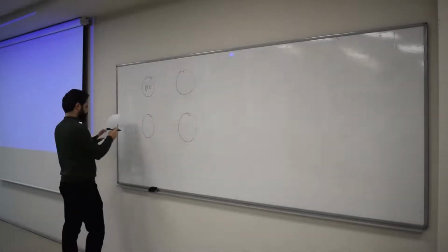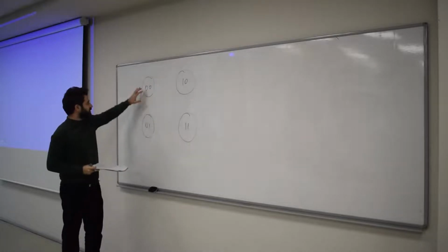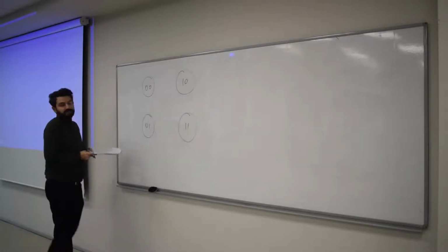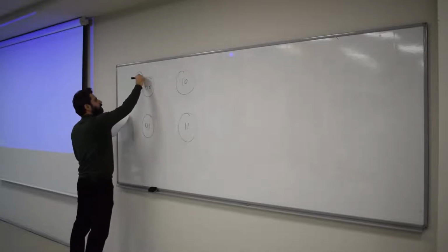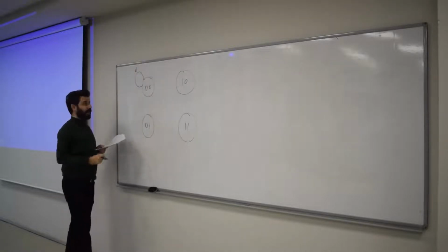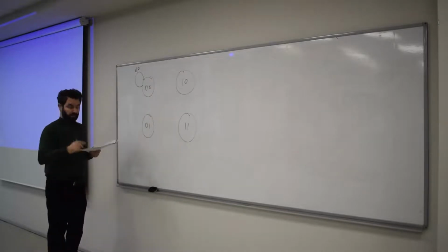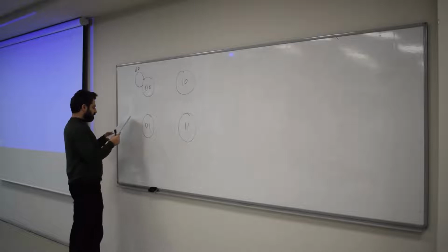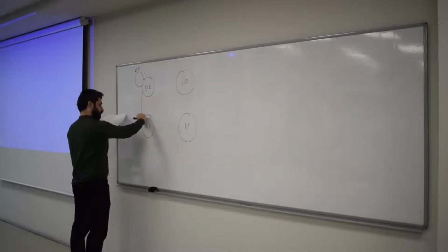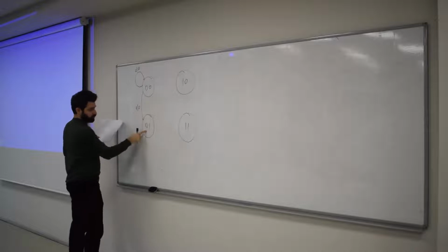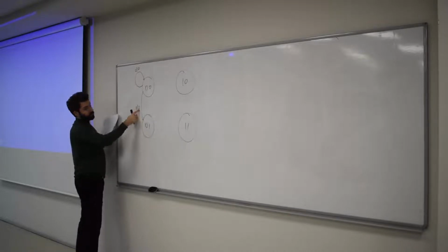So we got 0,0. We got 0,1 here, 1,0, 1,1. I mean, you can do it in any order, by the way. You can start with 0,0 and write 0,1 here. It doesn't matter, it will be the same. So whenever you have 0,0 in your flip-flops and the input is 0, you stay in the same state, and your output would be 0. Sorry, not 1,0. This is from the state table we drew last time. And whenever you have, in the same state, an input of 1, then what happens? You go from 0,0 to 0,1. The state changes, but the output also stays the same. In other words, the output is 0.